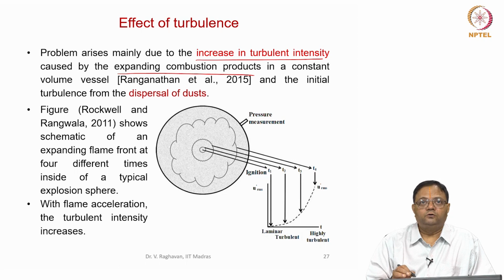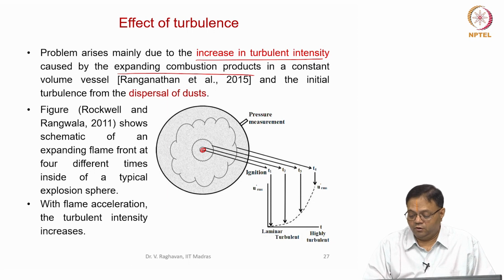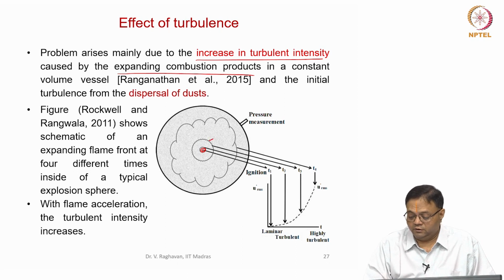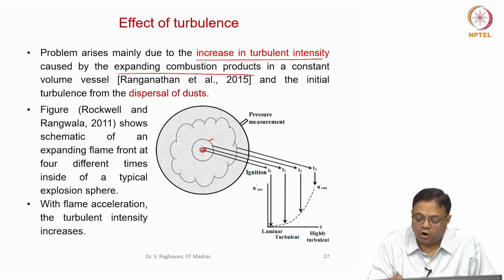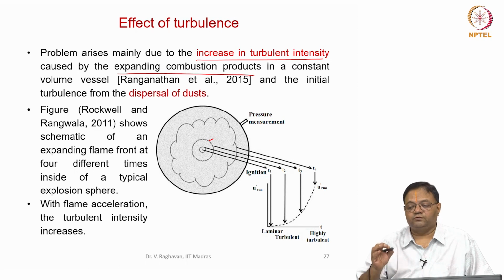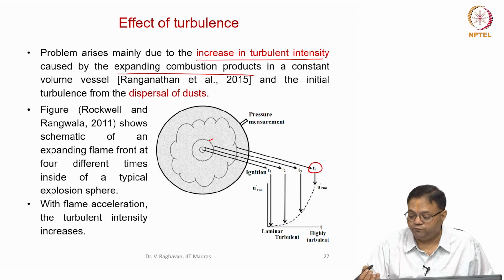For example, what happens when there is, as I told you, ignition, a small laminar flame forms. Okay, then there is some oscillations in the flame, you can see here. Now this has become a full laminar flame, you can see a clear circular spherical flame. There are edge oscillations, so turbulence is now onset slowly. Then after that you can see in this time it is fully turbulent.